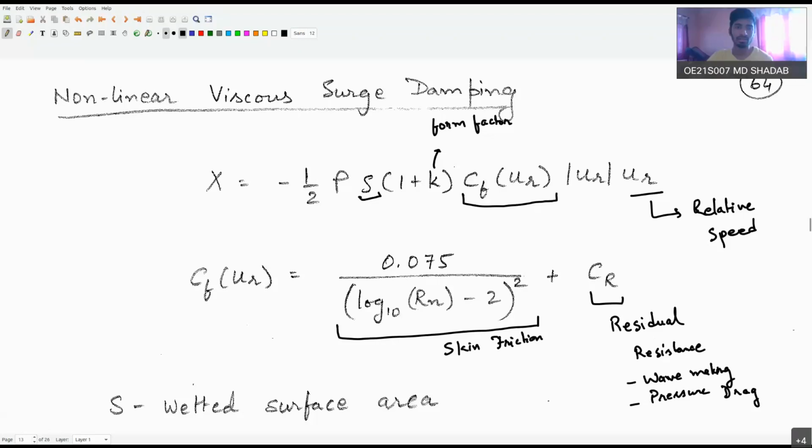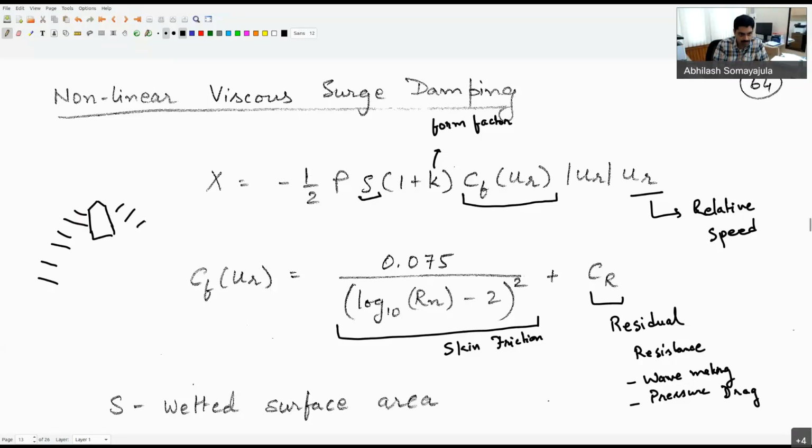So when you are moving the ship through the water, let's say calm water, you generally have a wave which gets generated, right? When we were doing the test in our wave basin also, there's a Kelvin wave pattern which gets generated, which means that if a ship is looking something like that, you'll see that there'll be a diverging wave which is moving away, followed by transverse waves which are moving to the back.